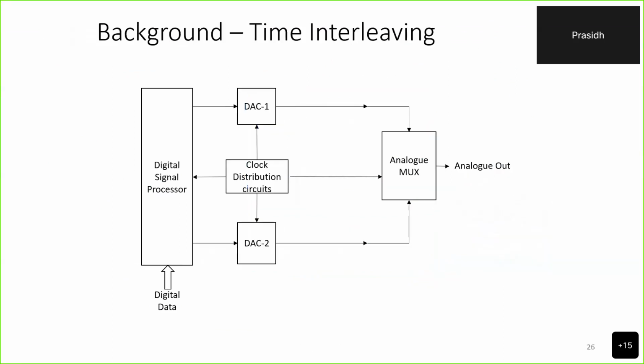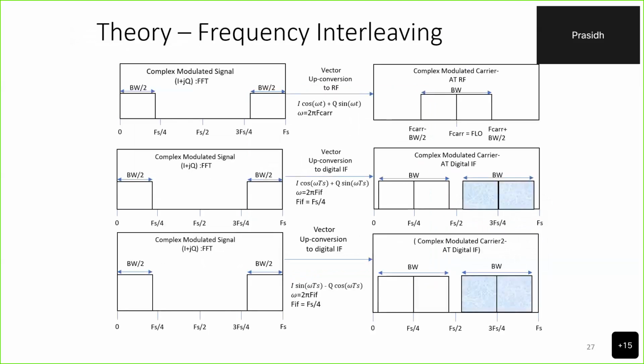Say, instead of going with 64 QAM, one goes with QPSK. 64 QAM has 6 bits per symbol, whereas here we only have 2 bits per symbol. So for the remaining 4 bits, the only way is either to extend the transmission time, or, if the transmission time is critical, or if it's a mission critical sort of application, we have to expand the bandwidth.